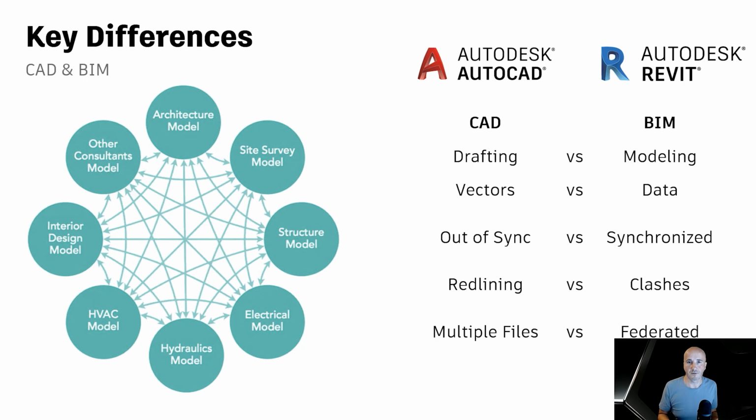Using a BIM approach with Revit, we create a federated building information model, an aggregated assembly of distinct models for each discipline, comprising a single complete model of the building. A single federated model is useful for design coordination, clash avoidance and clash detection, approval processes, design development, estimating, and so on. The individual models are maintained as separate files with clear authorship and scope definitions, but they are able to be brought together as needed.